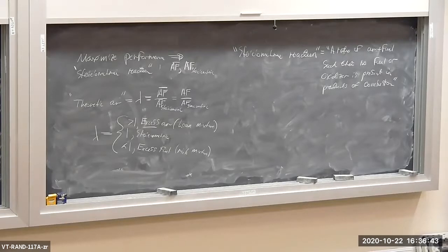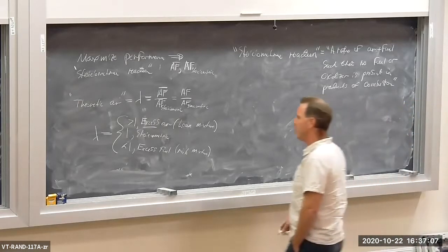Acceleration's poor, engines tend to overheat. The mixture can burn so slowly that when the exhaust valve opens, you can have actual flame coming out of the exhaust port. The air-fuel mixture can still be reacting, and that tends to overheat the engine, overheat the valve train.